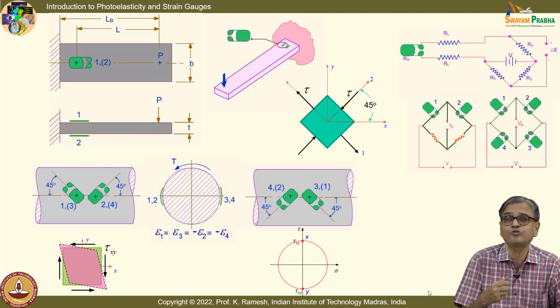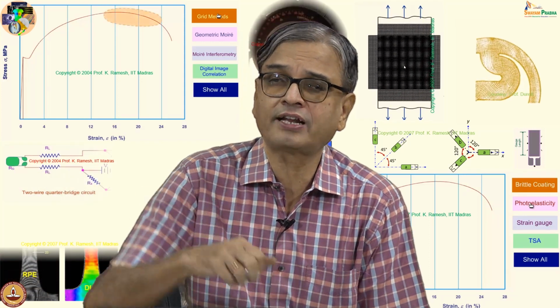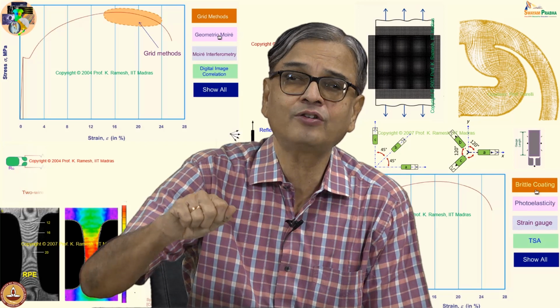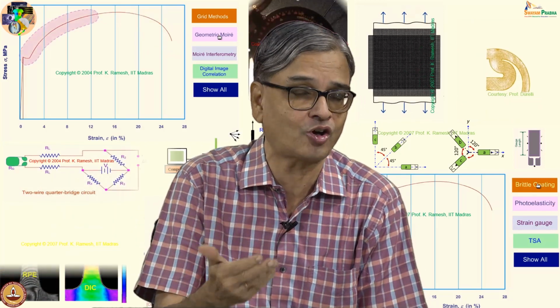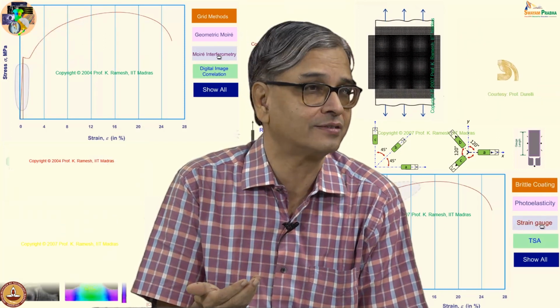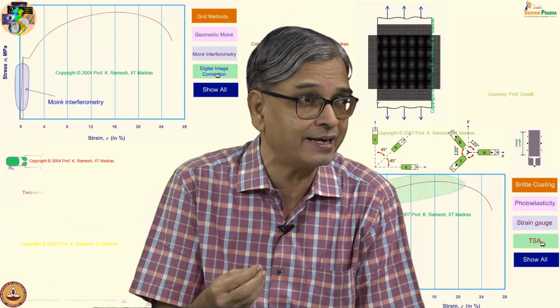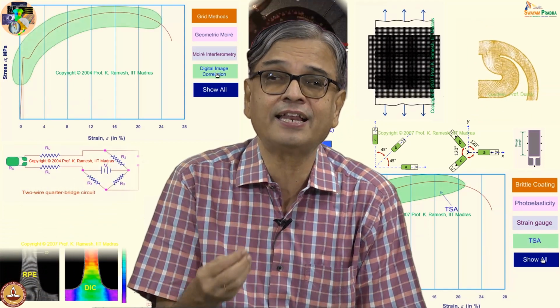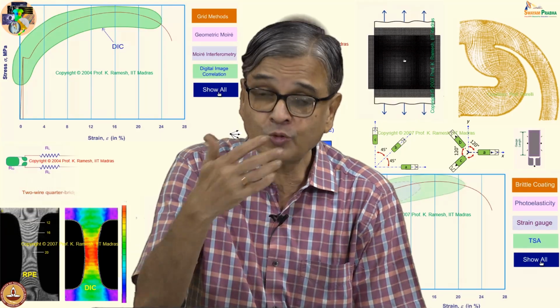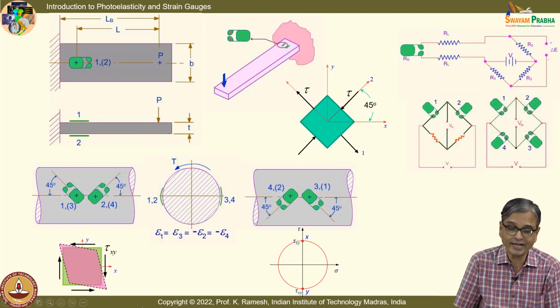So, if my interest is to find out torque, I said that you have to use a torque wrench when you want to tighten the bolt. When I want to have a torque wrench, I should have a system to measure the torque and give you that as a reading. There are many instances where you have to find out the torque. So, it is a transducer application. Your intention is to find out the torque applied. So, you design a mechanical element, a spring element, in which you place more than one strain gauge and connect them appropriately so that you amplify the signal. I can make a torque wrench using this as a strain sensing element, and I can amplify my signal.